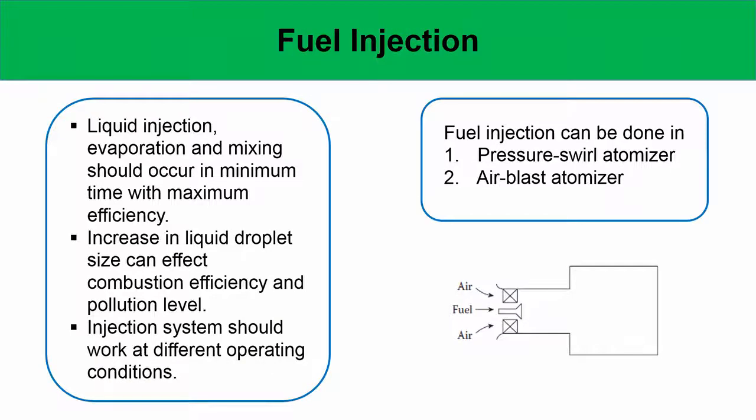First, you produce swirlers, which cause the liquid jet to diverge. Sometimes it is a hollow cone jet. So, you typically use a jet cone angle of about 110 degrees inside a combustor to ensure that the length of the combustor is finite. So, with all these criteria in mind, one has to design the fuel injection, and the whole purpose is that you have to create small droplets so that they evaporate quickly, and then after they evaporate, this fuel vapor can mix with the air and you can have combustion. So, that is the idea.